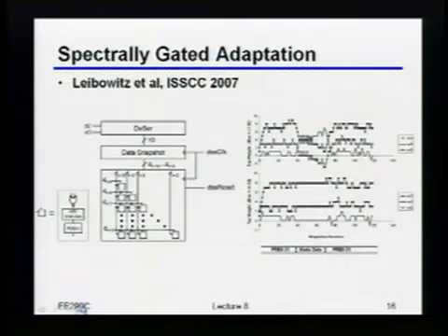Autocorrelate just means you take the data and you multiply it by shifted versions of itself. And if any of those shifted versions, times the original data, on average has some either positive or negative value, that means you're not sending something that looks white. Okay? Because white, remember, means the autocorrelation should be such that only the current sample is correlated with itself. Everything else should be completely uncorrelated, right?